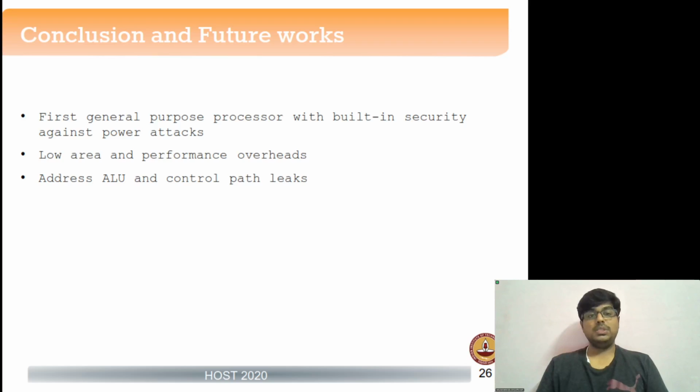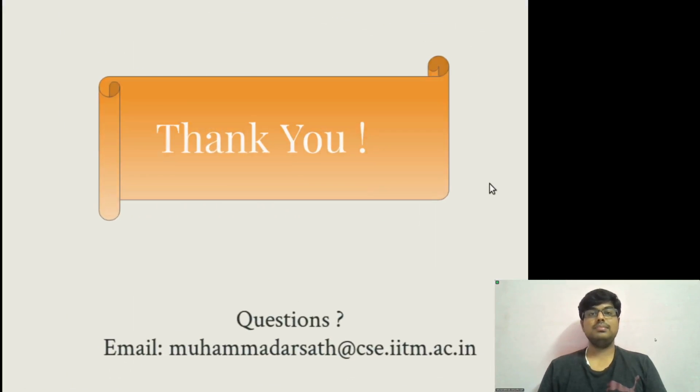To conclude my presentation, this is the first general purpose processor which has built-in security against power attacks. Since we are trying to fix the vulnerabilities at the ground up level, our associated area and performance overheads are very low when compared to work such as masking. Some of our future work is to address ALU and control path leakages. Thank you.